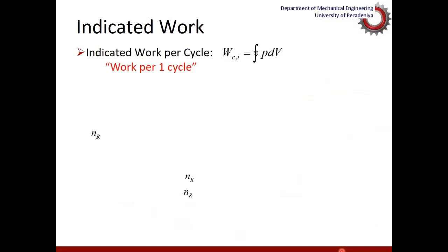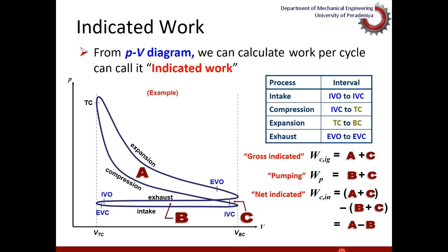Now, of course, thermodynamically, we can talk about these areas without any problem. If you have a diagram like this at hand, you can calculate this area and find out the work. But these engines operate at very high speeds, at least 1,000, 1,500 revolutions a minute. Therefore, one cycle will be completed in a very small time duration. So for a second, for a minute, there will be lots and lots of PV diagrams generated.